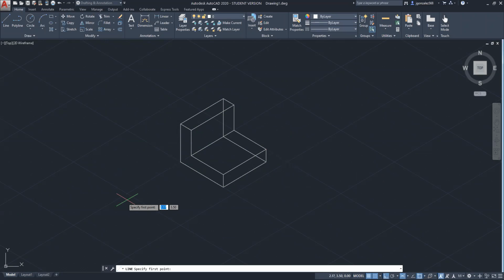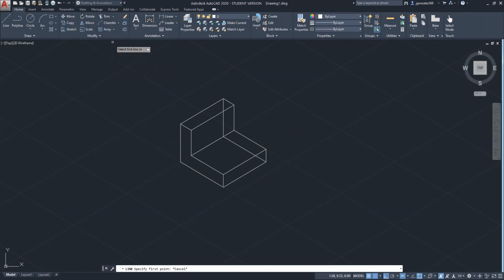All right. So now we're gonna do the chamfer. I have no idea how to say it. I always read it and then I forget later, but who cares? So change the fillet to chamfer. Choose distance of 0.5, enter 0.5.